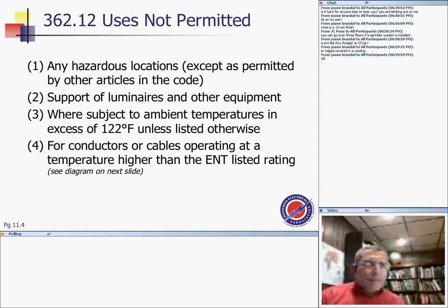So this is not permitted. Where can't you use them? It's not the conduit of choice for hazardous locations. There's always an exception in the code, guys, intrinsically safe systems and so forth. Support, how are you going to support? This is a conduit, this is pliable conduit. You can't support anything.